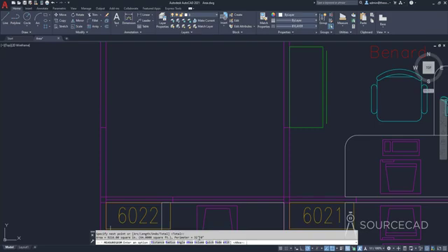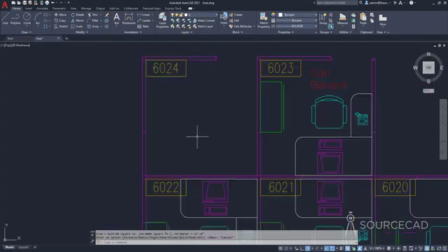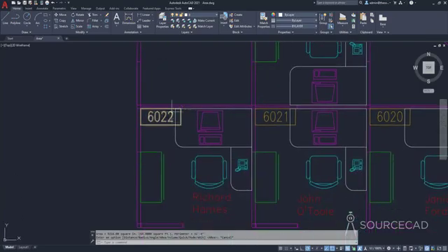So that's the easiest way of finding area, but it's not that easy when you have radii along the edges. For example, here in this case you can just select 4 edges and you can get the area, but what about this? We've got a table with these fillets, and now if you want to find area, you cannot select a perfect edge here. In this case you can use a simple workaround.